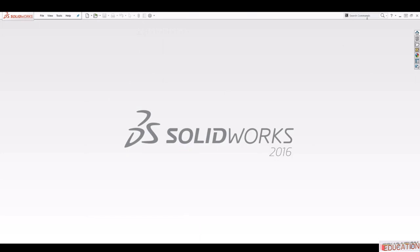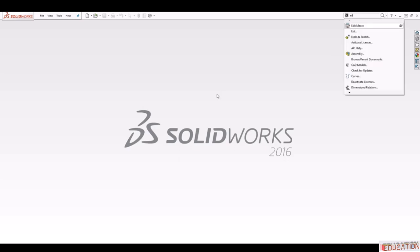And on this section over here you have the search option. It usually comes with the SolidWorks help, but I usually click on this drop down arrow and change it to search command. So when I'm in here, let's say there's a command you want but you don't know how to find it, you can type it in here, and as you can see, a list of commands would come up, and you can pick the right one.